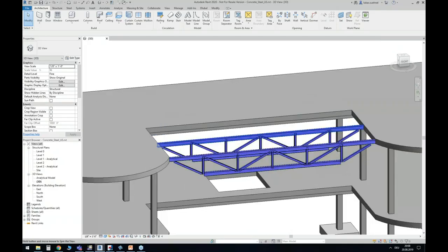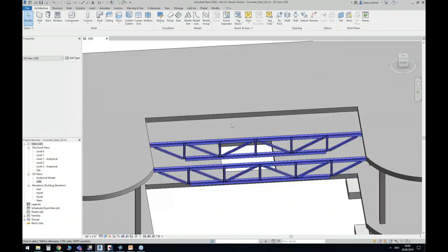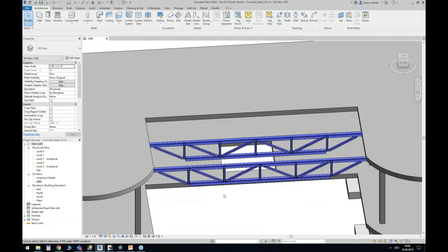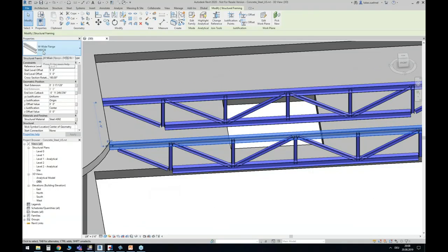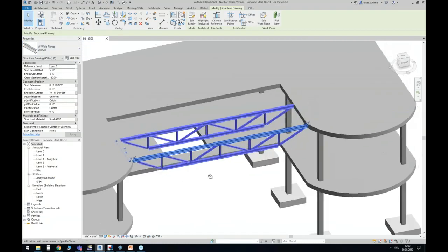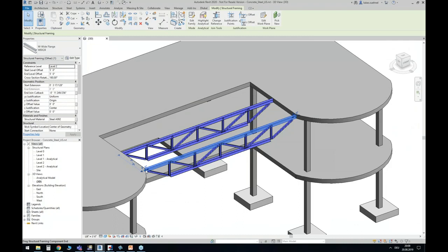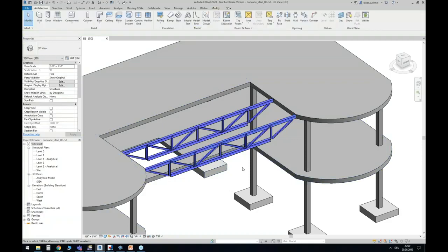Additional to that, we have a steel truss beam, where the upper girder is made of a W8 by 28 section. And just as a side information, the upper girder is one member that's running through. There is no division at the vertical or diagonal nodes.